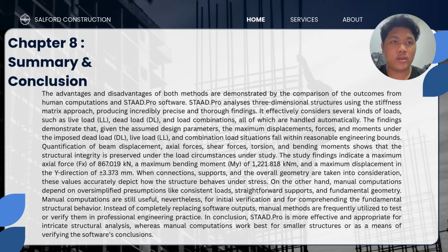I will be presenting about comparison between manual computation and StaadPro. StaadPro uses a stiffness matrix approach to analyze 3D structure, handling load like dead load and live load. And load combination automatically provides accurate result for displacement, force and moment calculation. For example, it records the first one, maximum axial force, is 867.019